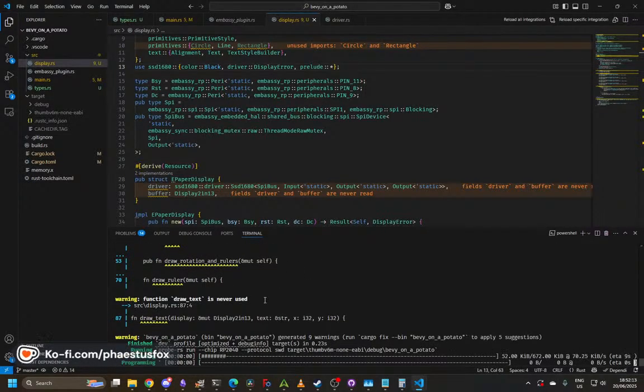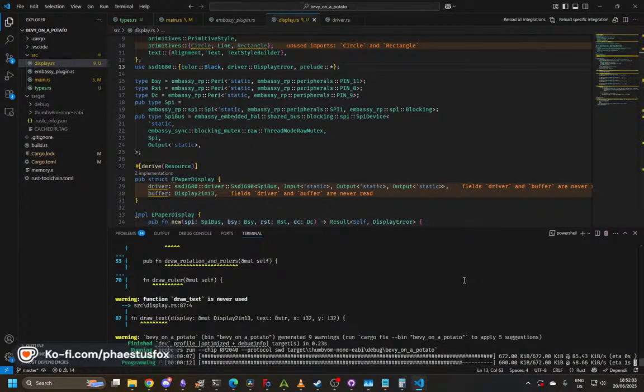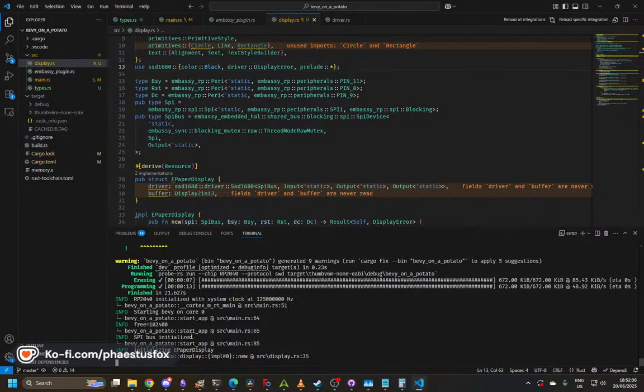Okay, so why are you not working? Okay, so we've got to initialize. So I said, what is the potential between ground and reset? Well, apparently the continuity is there, which implies they must be the same voltage. No, it doesn't, because it will tell me there's continuity if there's any voltage. Okay, well, they do have continuity.